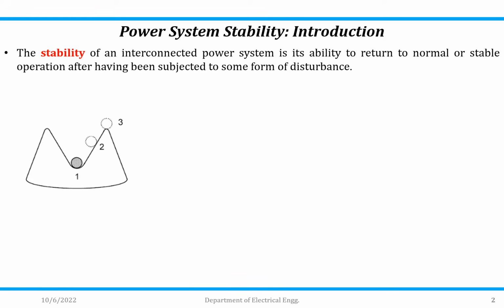If the oscillatory response of the power system during the transient period following the disturbance is damped and the system settles in a finite time to a new steady operating condition, then we can say the system is stable. And if the system is not stable, it is considered unstable. This primitive definition of stability requires that the system oscillations must be damped.